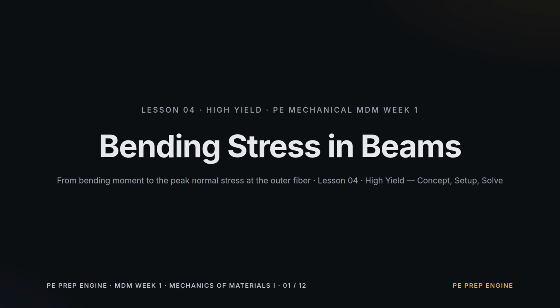That stress rides on the section's moment of inertia the way torsion rode on the polar moment. And before you can plug in, you have to find the maximum moment along the span. Get those three, and beam problems fall out fast.